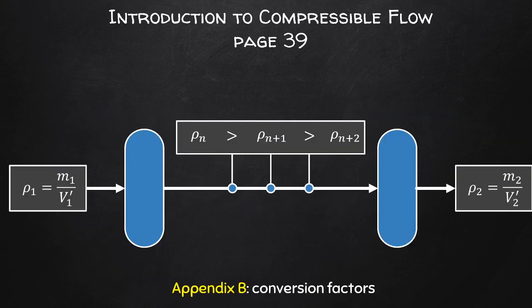Now, first off, how does one define compressible flow? Flows are typically considered compressible when the density varies by more than 5 to 10%. In practice, compressible flows are normally limited to gases, supercritical fluids, and multi-phase flows which contain gases. Note, though, that liquid flows may also be compressible under certain conditions. In practice, it is not possible for us to measure density, but since density is a function of pressure, which is easily measured, we use pressure instead to define compressible flows.